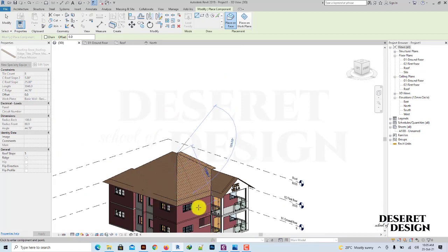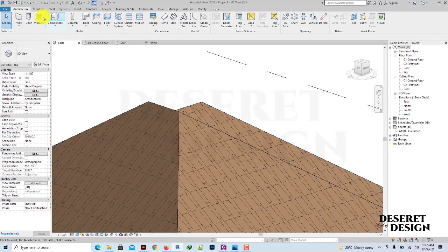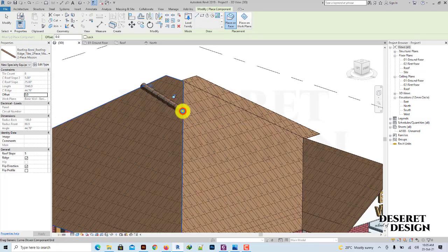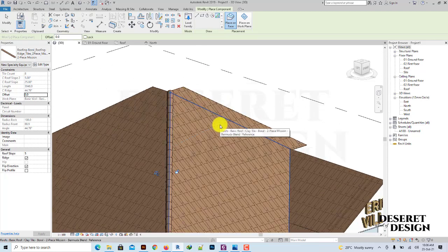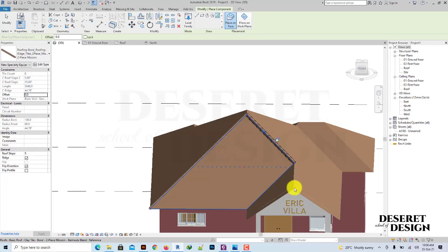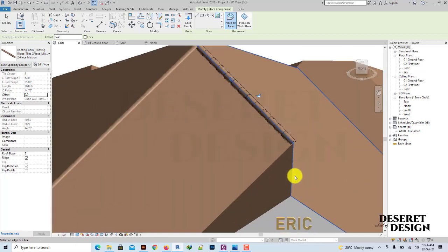Okay, it's supposed to even place. Oh, you can place it without drawing, right? So where is it? So component, we'll select it. We'll go to pick line. So you can pick the line, right? You can draw it, but pick line is faster. So pick this line. You see, so you undo. Then you come again. Make sure you pick the line very well.